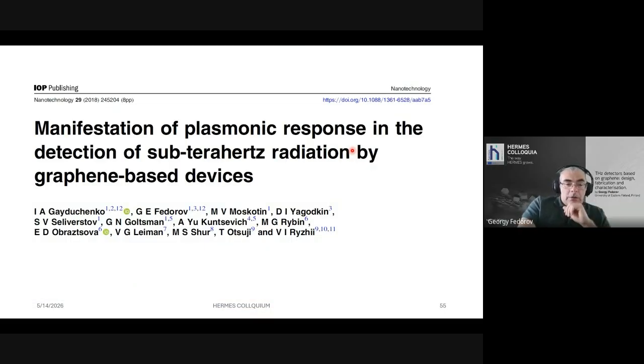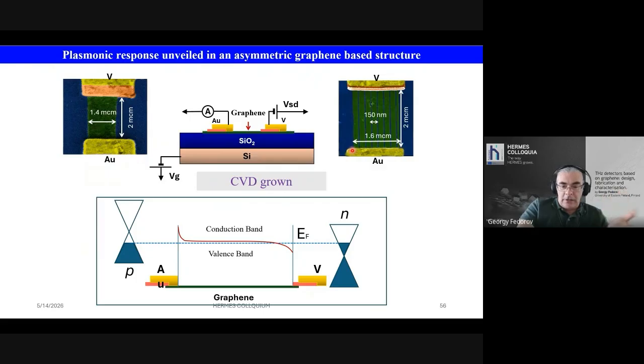Okay, this is work in which I participated. It comes from 2018. It's important for me because it illustrates two points. I start with the configuration of this device. Again, we were inspired by this work by Michael Fuhrer, and we were using contact doping, contact asymmetric metallization, to create photovoltage at the output. We were using not chrome and gold, we were using vanadium, and chrome and gold. The vanadium has an even smaller work function than chrome.